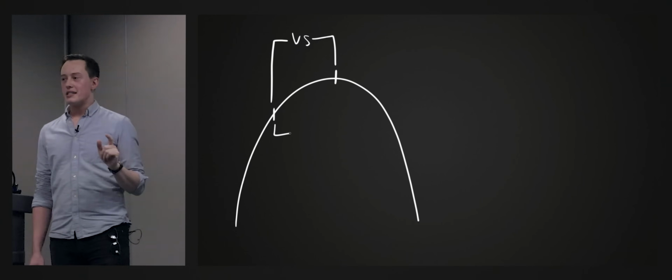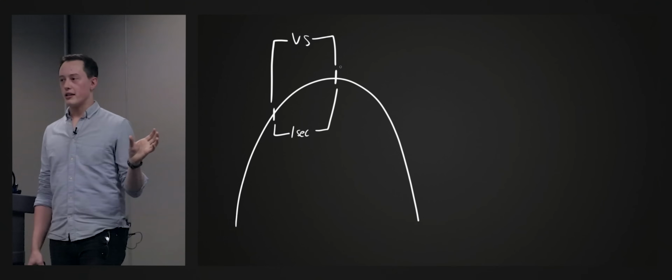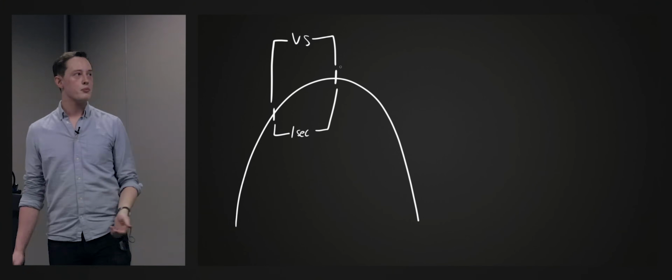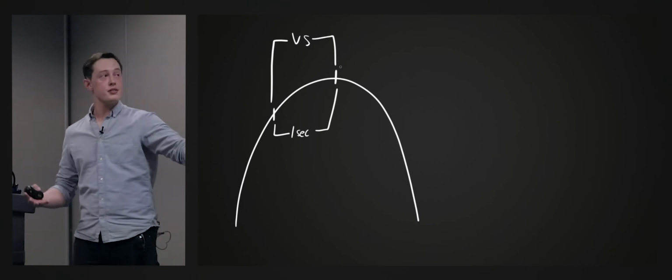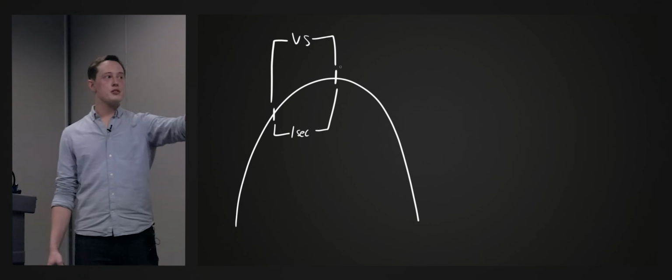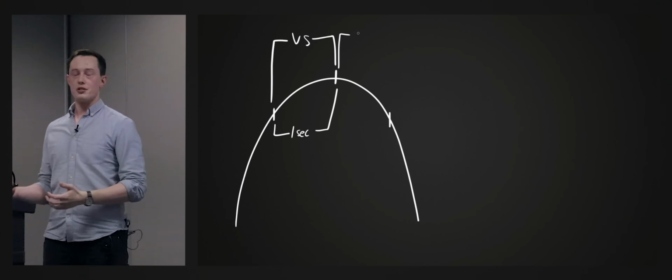And what we do to detect apogee, to figure out if we've passed that, is we compare two different readings that are 1 second apart. You can use any length of time for this, but I'm going to say 1 second for simplicity. If I'm at apogee, which we'll call 30 meters, and I look 1 second ago and we were at 25 meters, if 30 meters is greater than 25, we must be ascending or at apogee or close to it, right?